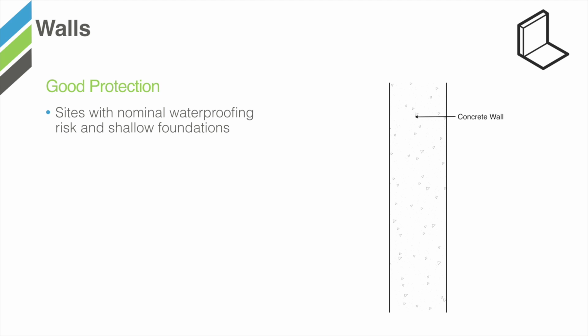On below-grade vertical walls, a number of steps need to be taken prior to the first application of polymer-modified asphalt. All concrete and form-curing agents must be removed, the surface must be cleaned, all patching must take place, and reinforcing any form tie holes must also be completed.